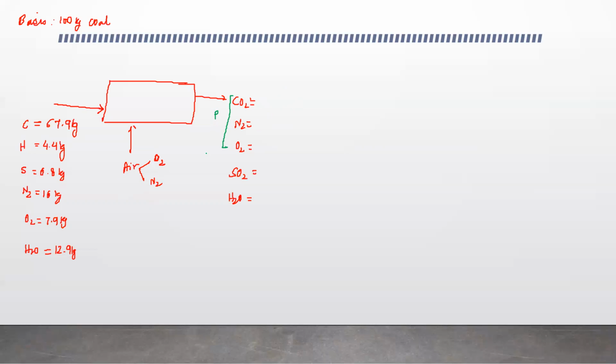Now, out of carbon dioxide, nitrogen, and oxygen, just think which of these three can be most easily found by stoichiometry or by some other balance? The answer is carbon dioxide, since we have carbon here and carbon coming in from nowhere else.